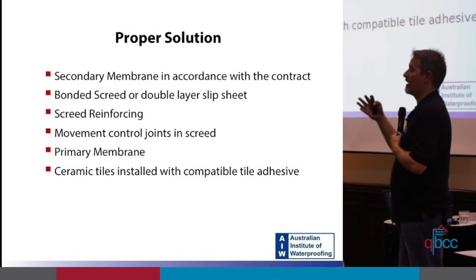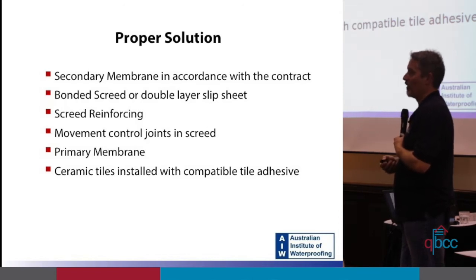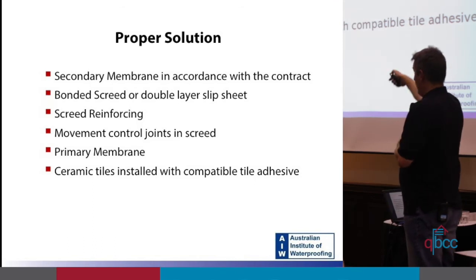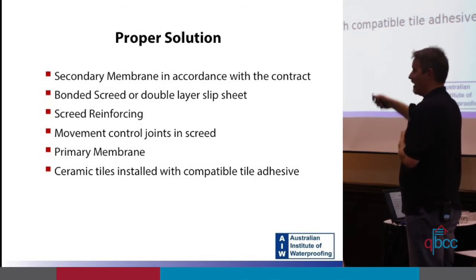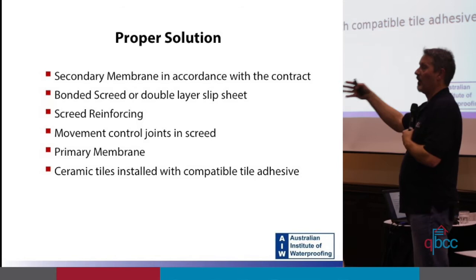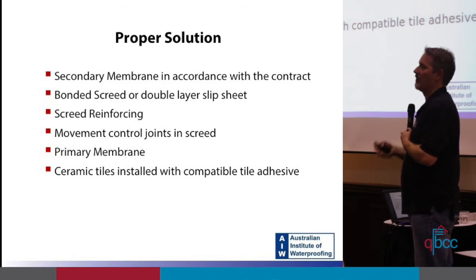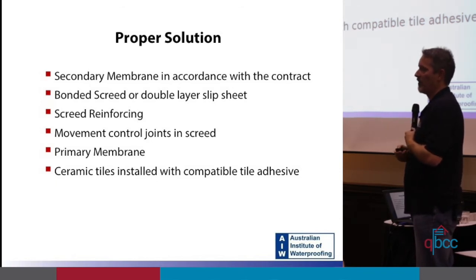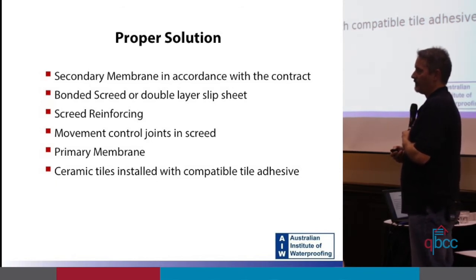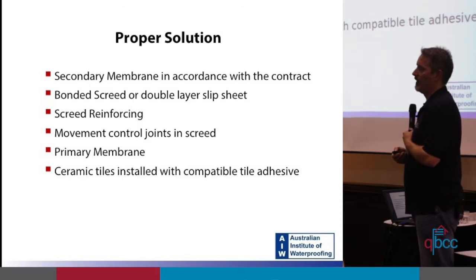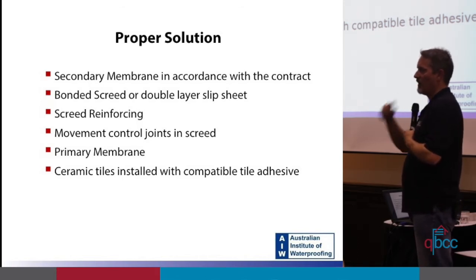Okay, so people always ask me, oh yeah, they're going to be full of glue and full of grout. Well, they can't be, right? So you need to design the movement control joints in the screed. You actually got to plan your tile layout before you even go there, right? So it all lines up. And then the control joints have got to be free of tile adhesive and free of grout residue. And the best time to do that is while the tiles are being laid, while the adhesive is still wet. Right? Clean the movement joints out as you go.